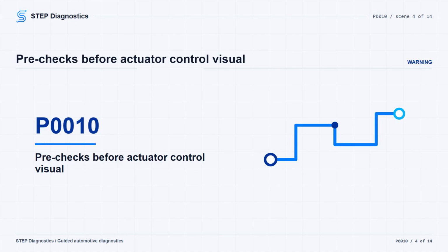With the ignition on and the vehicle in service mode, first make sure there are no related crankshaft or camshaft position codes active. If those are present, check what they mean first, because they can affect how this test behaves. If none of those related position codes are set, check the oil side before blaming electronics. Oil level, oil condition, and oil pressure are critical to this cam actuator system. Dirty, contaminated, low oil, or low oil pressure can all affect actuator operation.